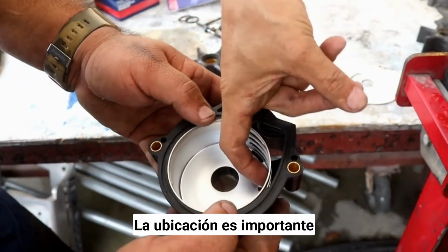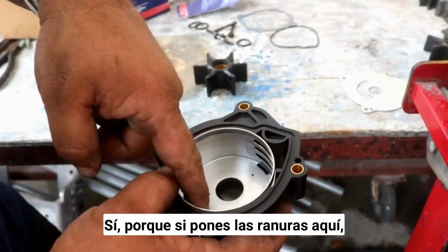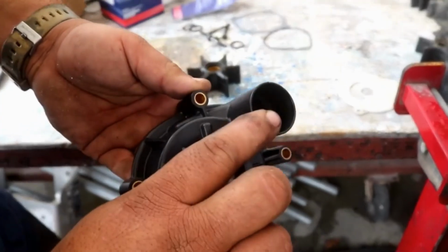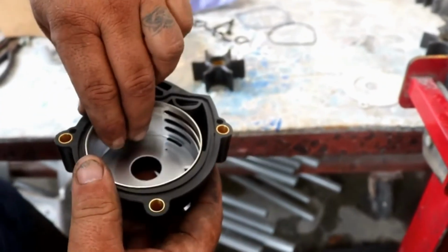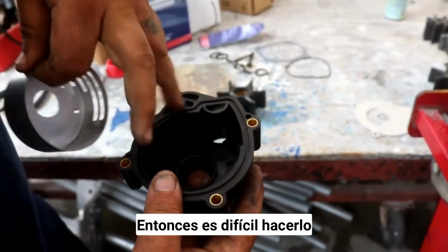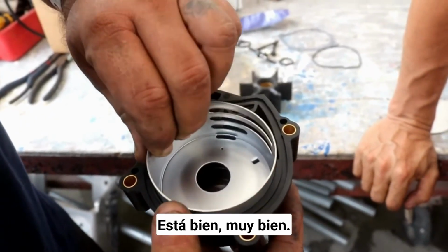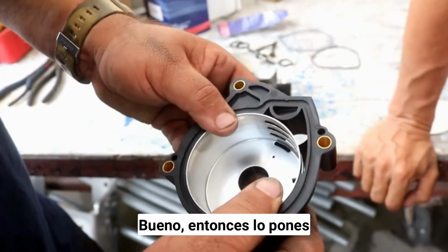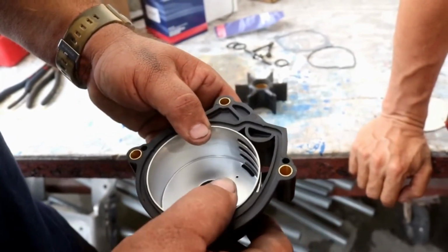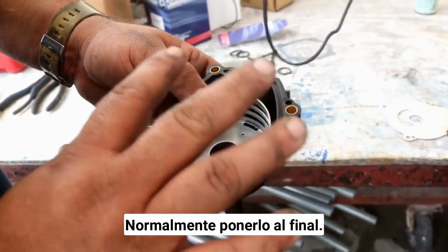It's important, the position of those grooves. If you put the groove here, the water will never go up through here. Also, it has little slots, so it's hard to make that mistake. Then you put it in there, and that's it. You have another O-ring here, and I usually put that towards the end.